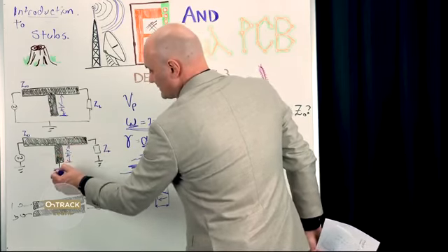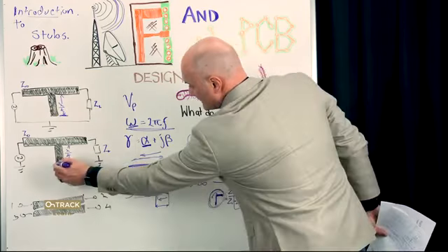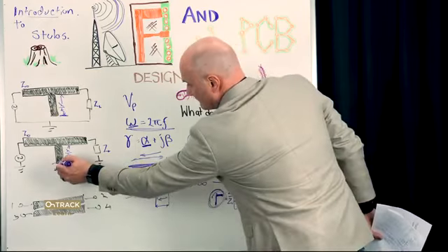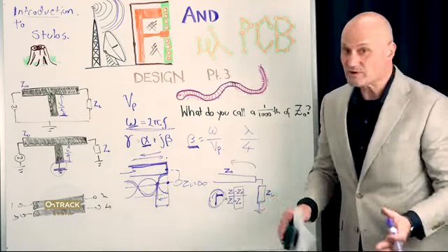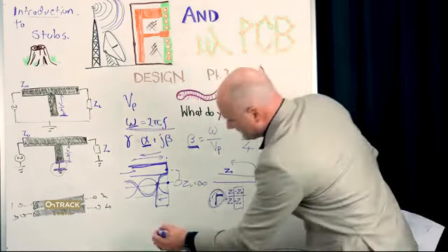The same thing happens, only here the current is 0 instead of the voltage, and at the shorted end the voltage must always be 0 because it's terminated at ground, assuming your ground is very good. And of course, there's ground currents and things like that too. So you want to have a very solid ground plane and via stitching and all those things. The reason RF engineers want those things on a PCB is to make sure your ground is as ground as possible.